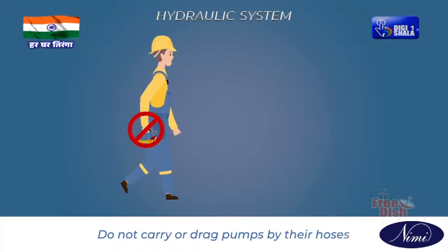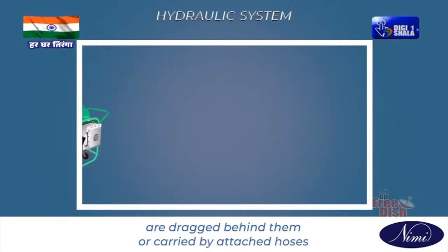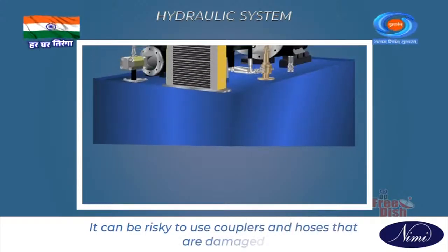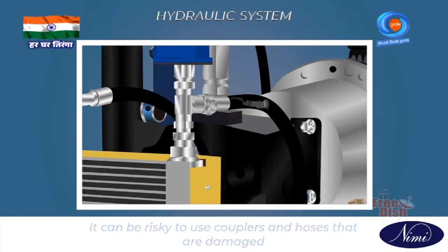Do not carry or drag pumps by their hoses. Couplers and hoses can be harmed if rams or pumps are dragged behind them or carried by attached hoses. It can be risky to use couplers and hoses that are damaged.